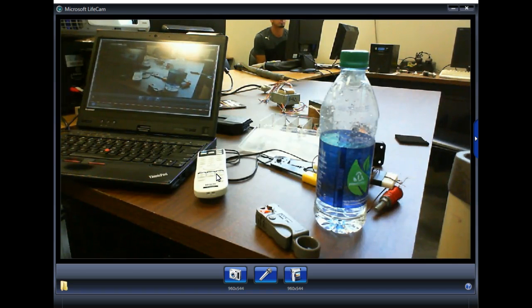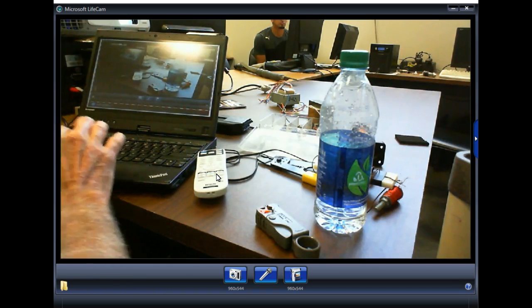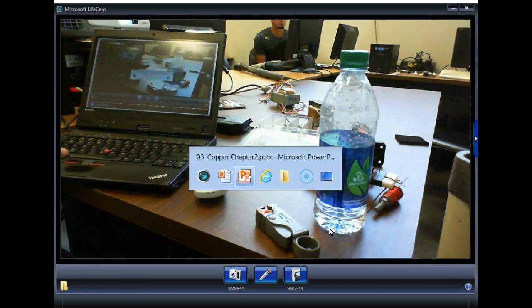When you splice it, you can't just cut the wires, strip them off, and twist them together, because as soon as you do that, you mess up that spacing between the inside conductor and the outside shield. So it takes a little technique to learn how to splice that. You have a special splice that we use to actually splice the cable.